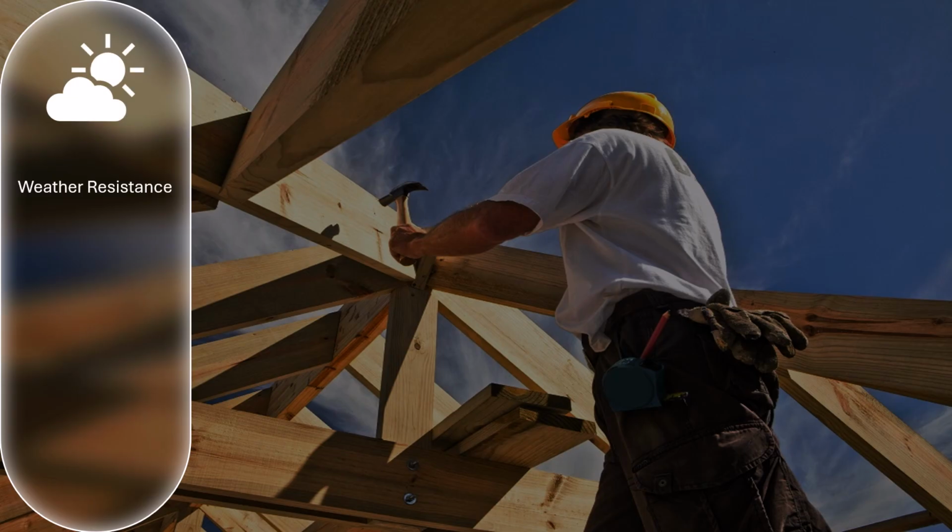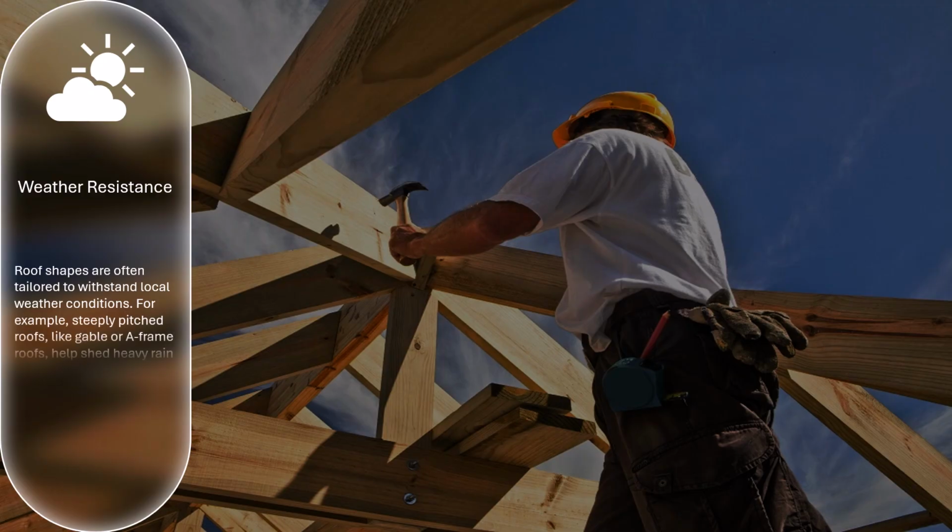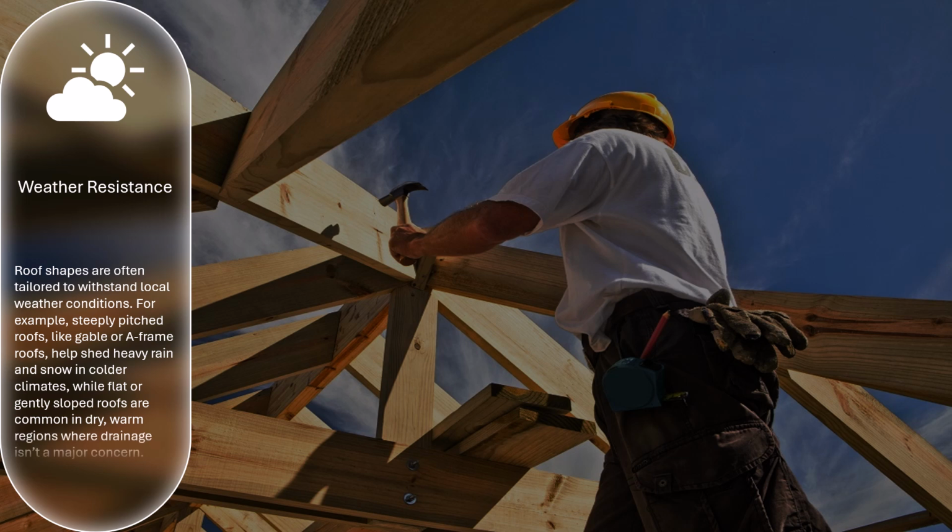Weather resistance. Roof shapes are often tailored to withstand local weather conditions. For example, steeply pitched roofs, like gable or A-frame roofs, help shed heavy rain and snow in colder climates, while flat or gently sloped roofs are common in dry, warm regions where drainage isn't a major concern.